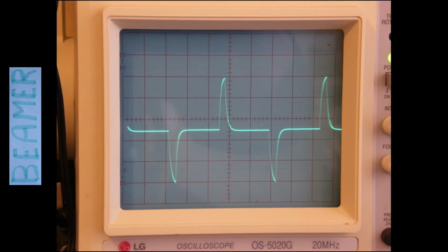It's as though you've put a square wave through a capacitor. This can be used for many applications and is a very classic trace. And there we are. You can generate many permutation traces with this little circuit. All you have to do is change the resistors, or put a diode in, or remove resistors, or change values of resistors.